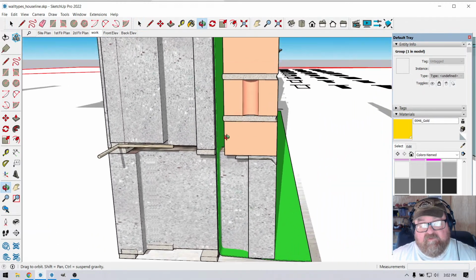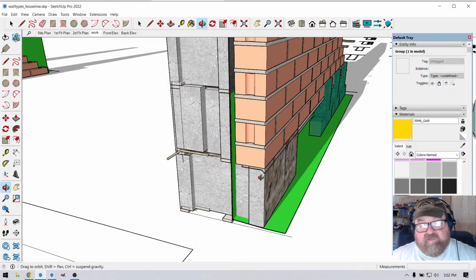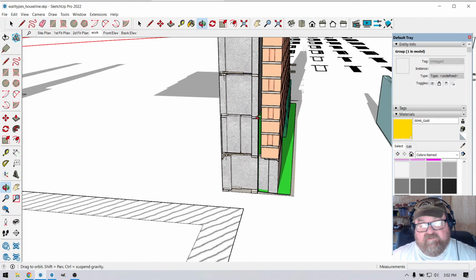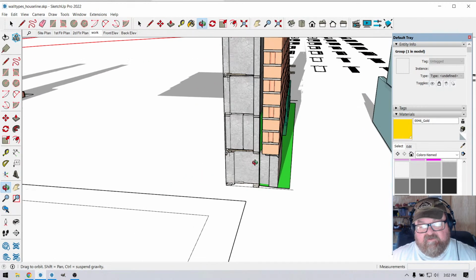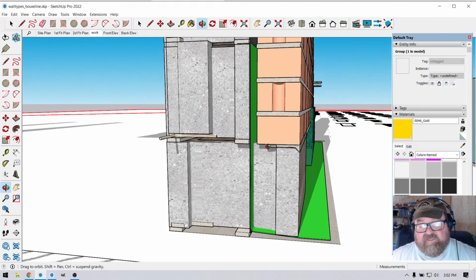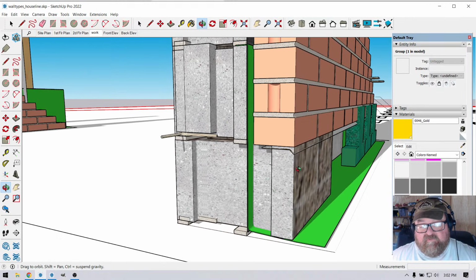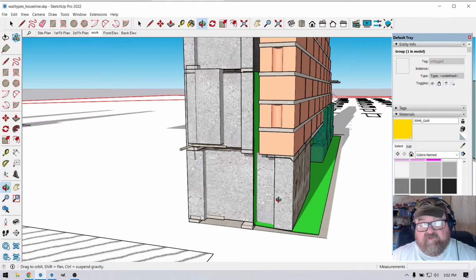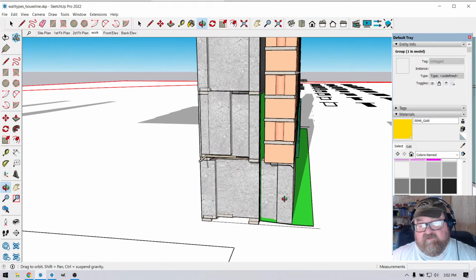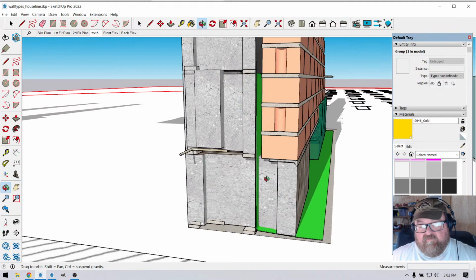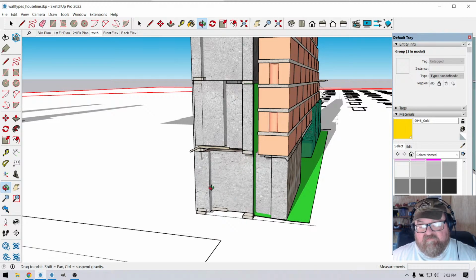But the thing about the brick is that most people think there's this huge air gap in there. Okay, there's not, because the thing you set it on is a 12-inch. Typically, 99 out of 100 homes that have brick on them will have this 12-inch course sitting either on the footing or a couple of rows up.